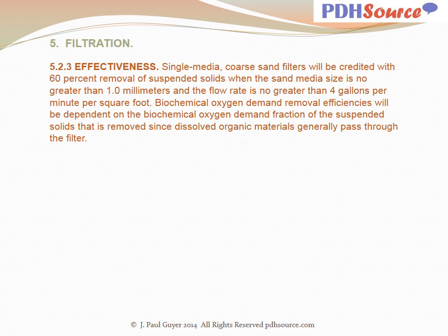Single media coarse sand filters will be generally credited with 60% removal of suspended solids when the sand media size is no greater than 1 millimeter and the flow rate is no greater than 4 gallons per minute per square foot. Biochemical oxygen demand removal efficiencies will be dependent on the biochemical oxygen demand fraction of the suspended solids that is removed, since dissolved organic materials generally pass through the filter.